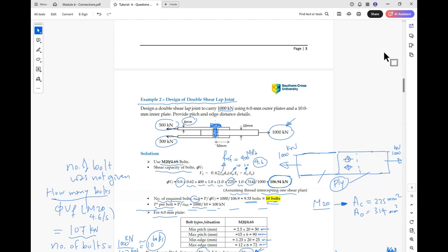So what you need to do is just find the load combination, find the maximum uniform load on the beam, and the load on the column will stay the same, 2 kilonewton per meter. Then you can determine the reaction and the bending moment and so on, then design the rafter for the moment and shear, design the column for moment and normal force, and design the connection.